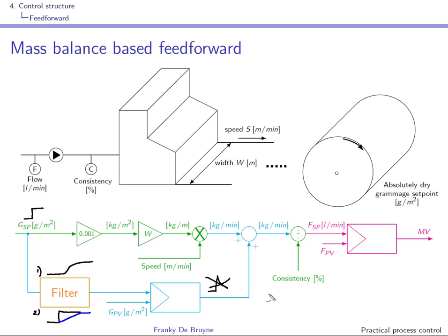And a third methodology, which can be used if you're using a PID controller that has this functionality, and we'll see this in the next section on the PID controller, is to use a controller that uses a proportional error, that is b times set point minus PV, right?